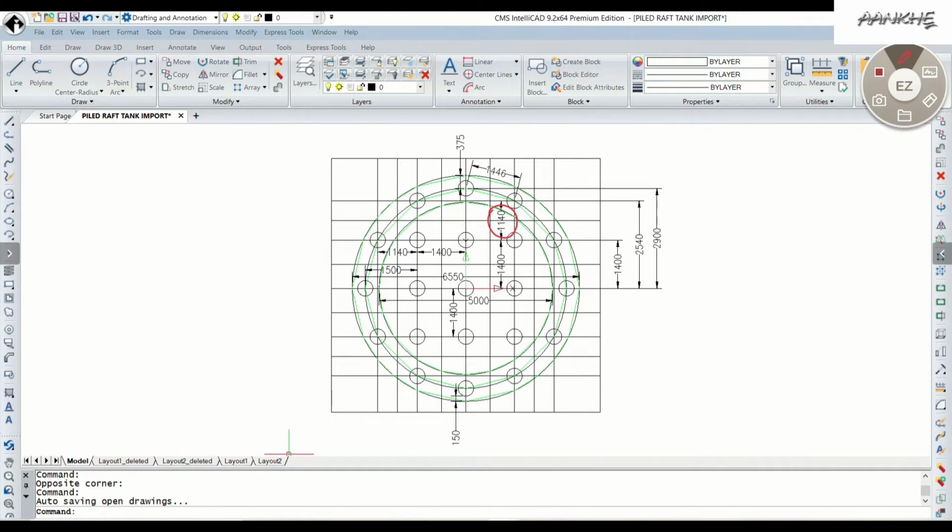That means if we take 450 into 3, if the spacing between the piles is less than this, if S is less than this, then 90% of total group capacity will be considered, right? So in our case, you have to consider 90% of the pile load capacity.